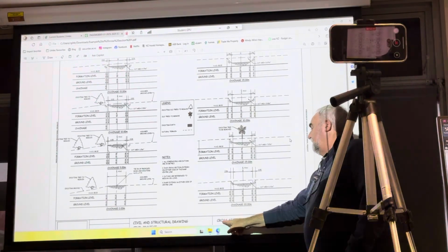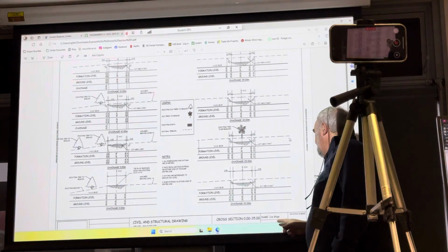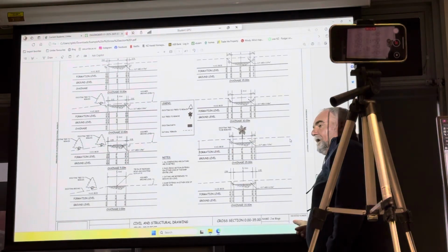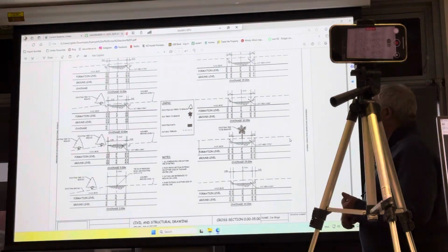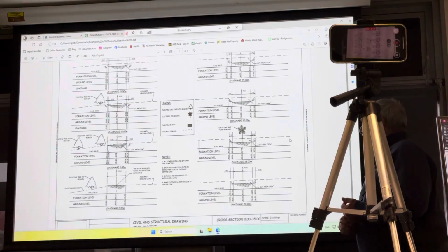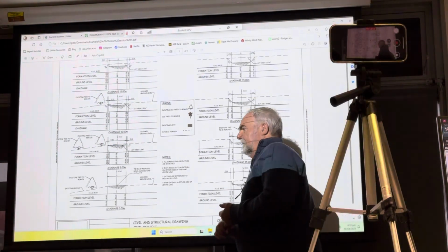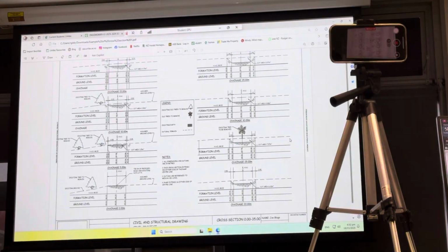The changes are reflected on the drawing sheet if you're looking for something to put on your drawing sheet, and it should be sheet 1 of whatever it is. Your first sheet is going to be your site plan. The second lot of sheets will be your cross sections of whatever order I've asked them for, and the last sheet will be your long section. I'm pretty sure that's the way I've asked.